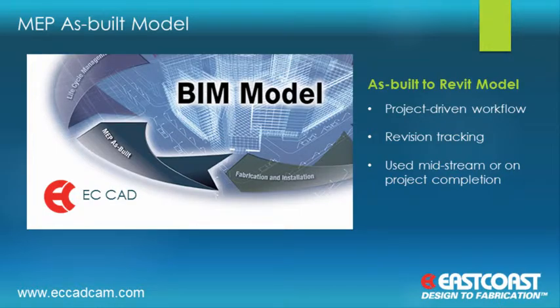Any number of drawings can be added to a Revit project in this manner. And if you need to make changes to the drawing, you can bring the updated data into the EC project again, so that you can bring the updates into the Revit model. These revisions are tracked and stored in EC project. In Revit, you can choose to bring in the most current revision that has been committed to the project in the CDM or previous versions if needed. The system provides you with the flexibility to prepare the as-built as portions of the project become installed, or wait till the entire project has been completed.